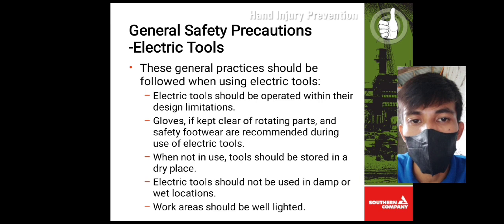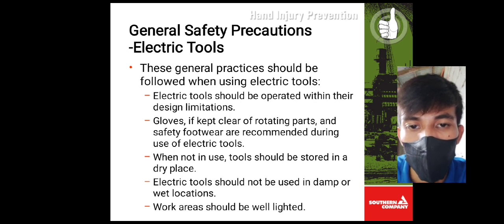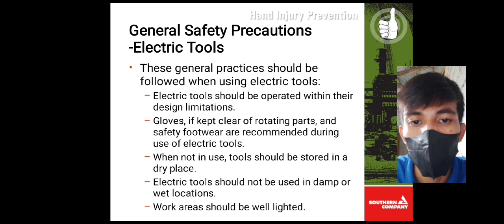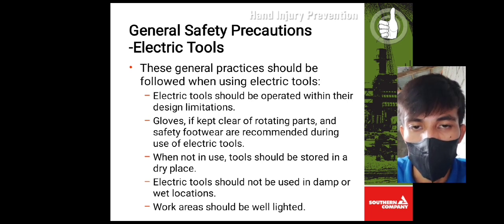These general practices should be followed when using electric tools. Electric tools should be operated within their design limitations. Gloves, if kept clear of rotating parts, and safety footwear are recommended during use of electric tools. When not in use, tools should be stored in a dry place. Electric tools should not be used in damp or wet locations. Work areas should be well lighted.